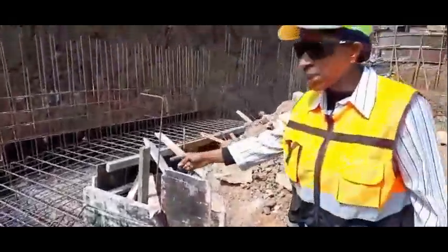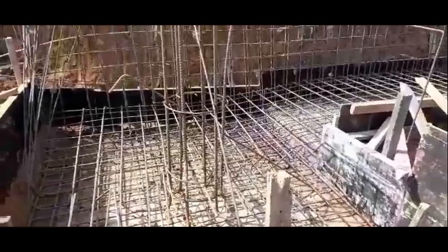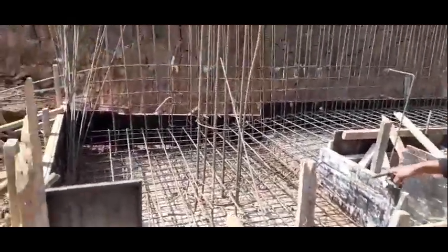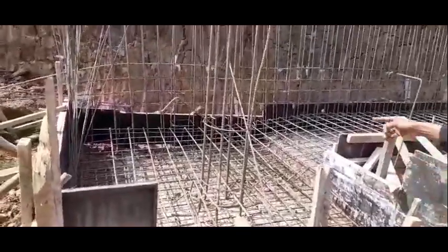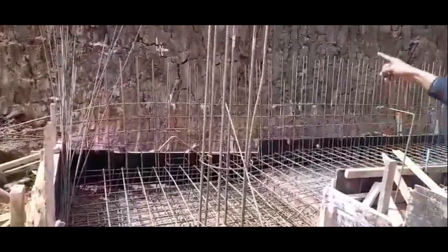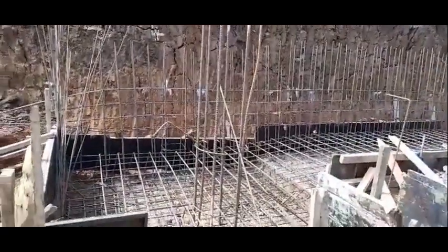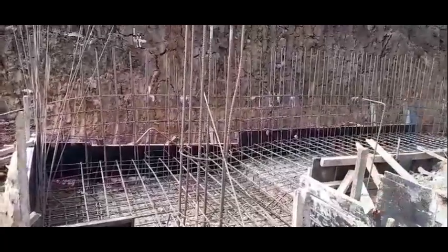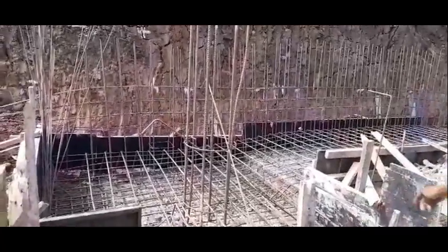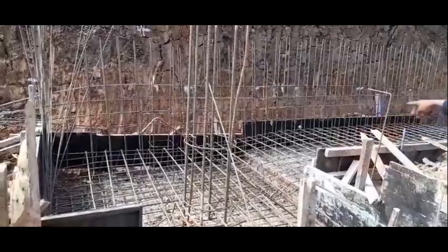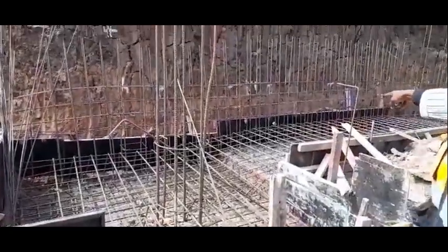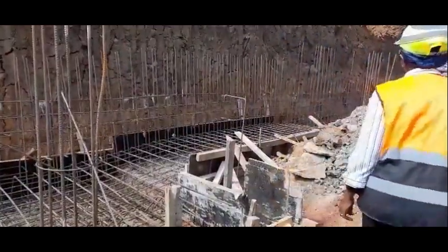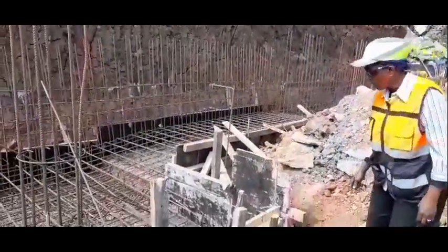This is a column base with some reinforcement, as you can see, and the reinforcement is placed in two directions as shown. The vertical reinforcement bars you see are called starter bars, and this being a second basement, there is some retaining wall, and therefore the big column base is integrated with the footing for the retaining wall. So this is an example of how we place reinforcement.